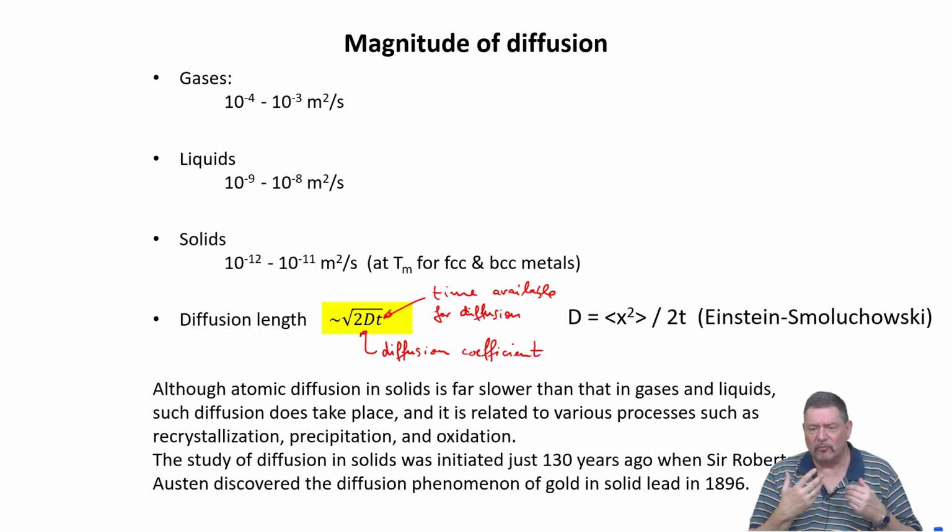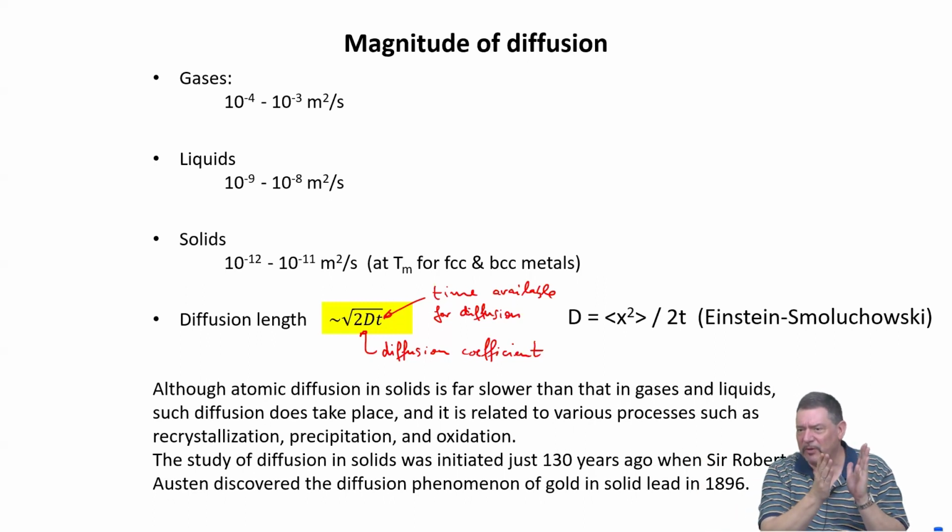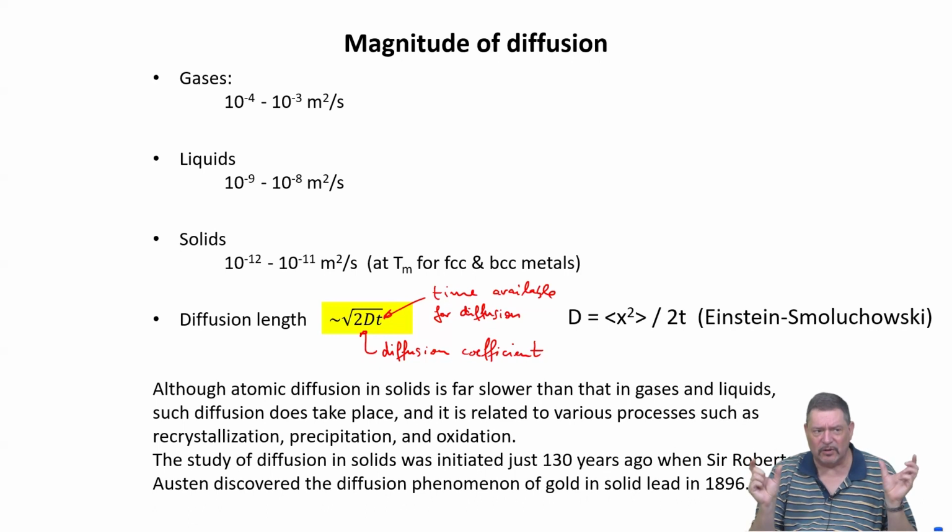And when we measure diffusion, we always measure, let's say, how a material as a whole moves into a certain direction. So we need to have a gradient of property, concentration, or having different number of neutrons in the core. But it's still the same thermal motion, which means that we can apply this diffusion length estimation based on the atomistic description of Brownian motion in a system not containing a concentration gradient. That was treated by Einstein and Smoluchowski.